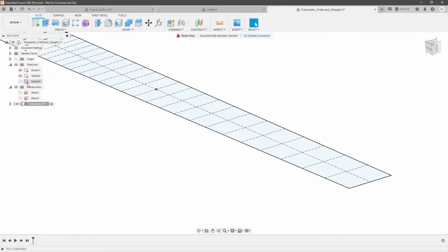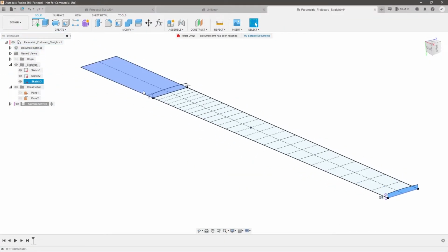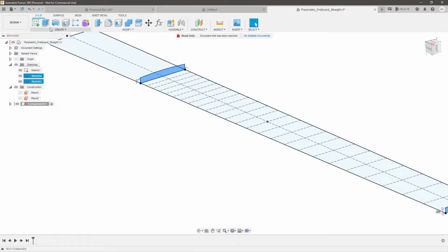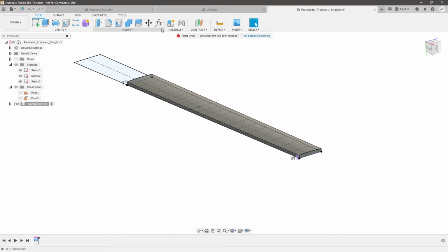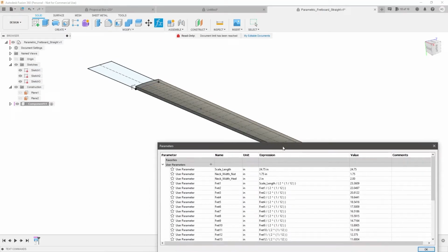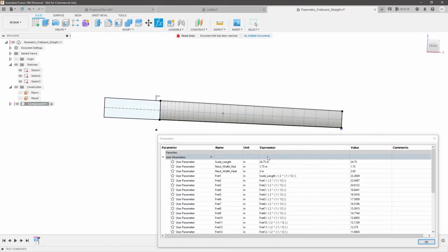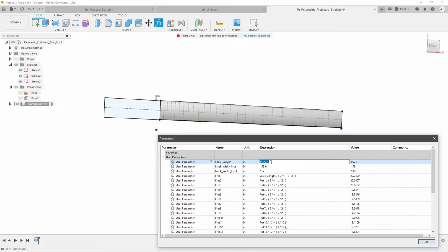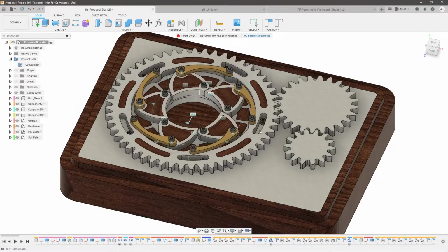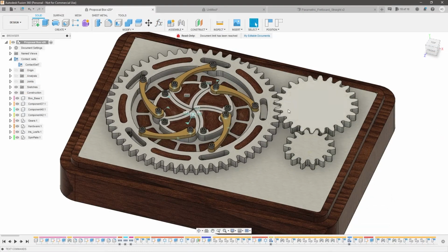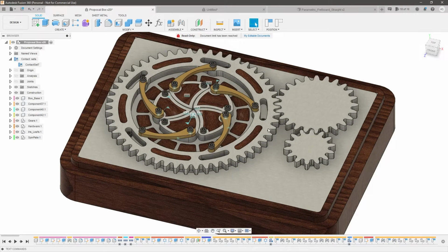The other school of thought is top-down design, where you start with the assembly file and then create each component within the context of that assembly. This means that the dimensions of parts can be more readily driven by other features or components in your design. This is extremely useful when building parametric shapes and features, and can make life much easier for developing new products when you may not know exactly what the dimensions of any given part should be.